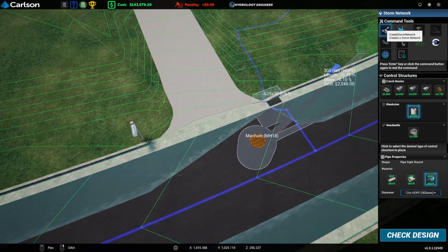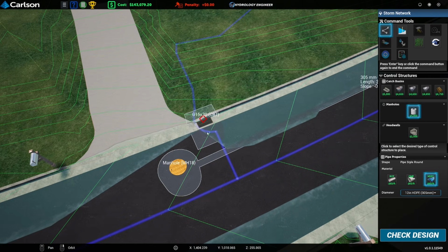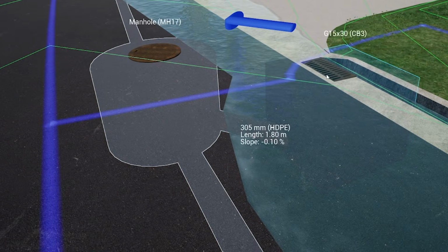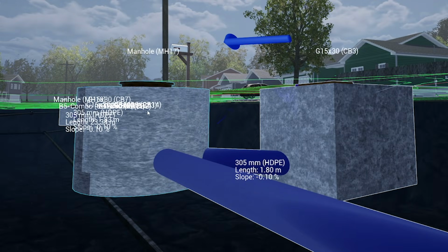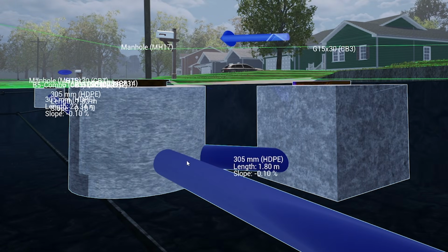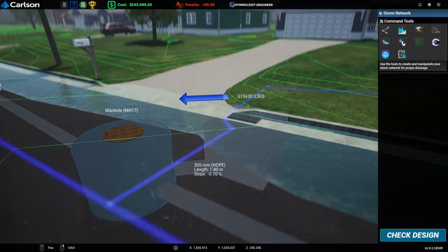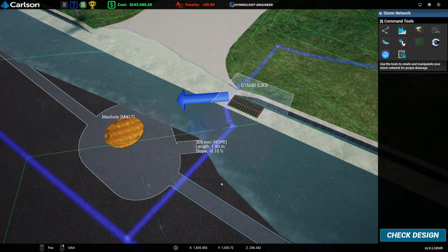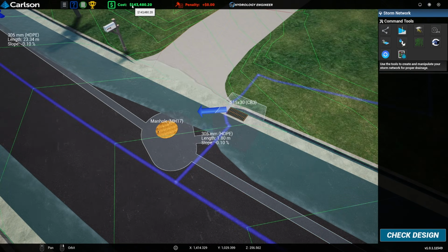Now it's worth noting, we wouldn't always connect these gullies to a manhole. We would be able to connect them to a pipe. So out of this gully, rather than connecting to this manhole, we would just branch onto the pipe, because you would still be able to access it to clean from this gully. It's not actually best practice though. Best practice is to do what we're doing here, but obviously this is really making the cost add up, because